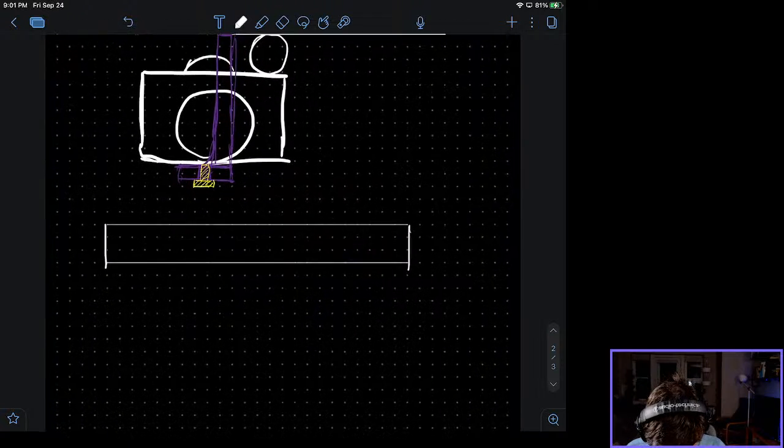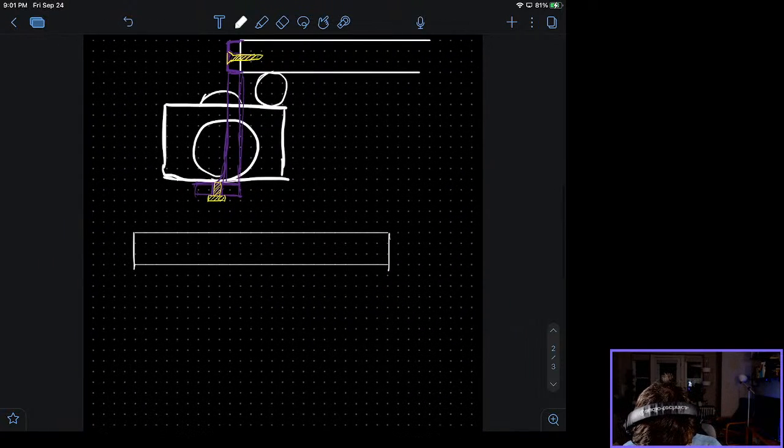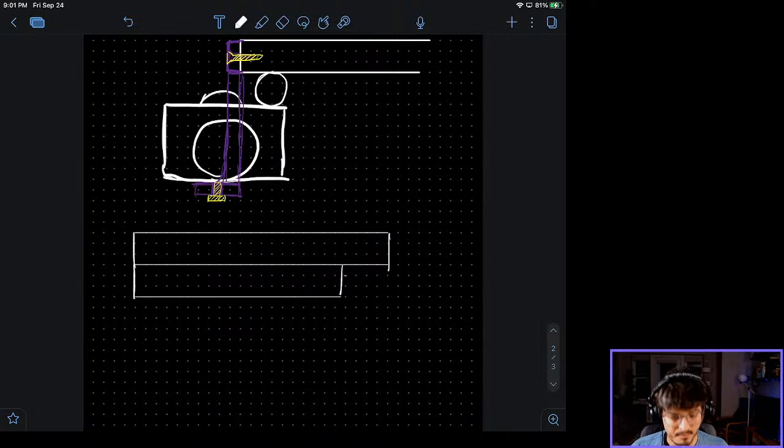Anyway, so we have the shelf right there. We have the pipe that pretty much ends like this. It is about a 3/4 inch pipe as well, so it's about the same thickness as the piece of wood. And if I go back and draw the part, let's give it a round edge on one side, another round edge on the other side. We'll do the holes for the screws, and this is for countersunk screws. So we'll have it like that.